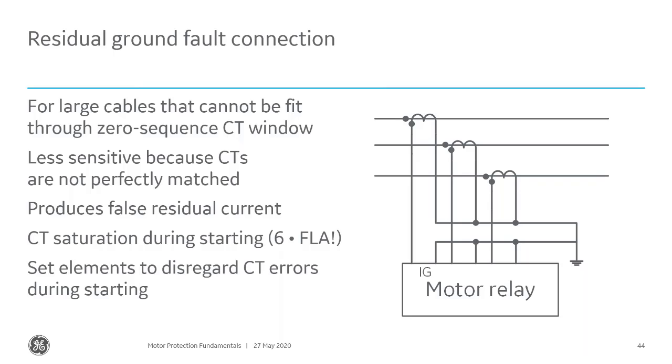Well, I could have 10% inaccuracies in my CTs based on the C37 standards that CTs are built by.